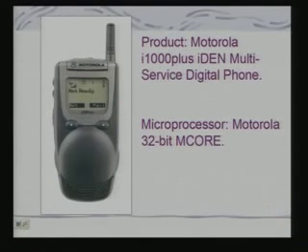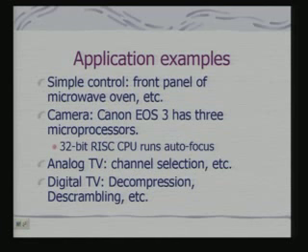And what I would like to show is, in these cases, the different types of microcontrollers that are being used. This PDA uses a 32-bit microcontroller. Another example is that of a cell phone. It also uses a 32-bit microcontroller. Then if you look at a household appliance example, the front panel of a microwave oven, that also uses a microcontroller, but typically it will have its word size much smaller than that of the earlier examples, because the functionality that it handles is much less.